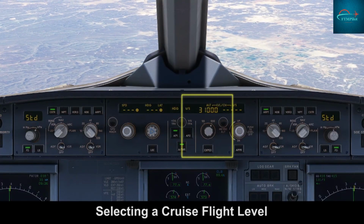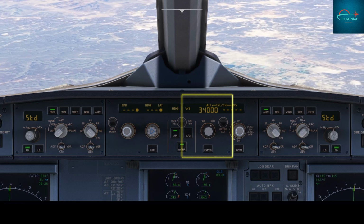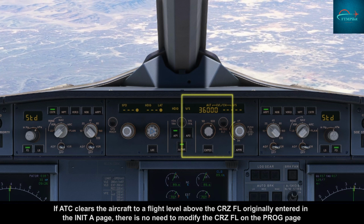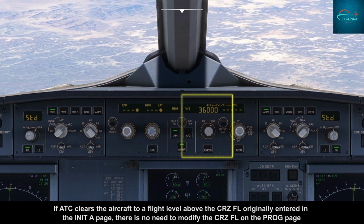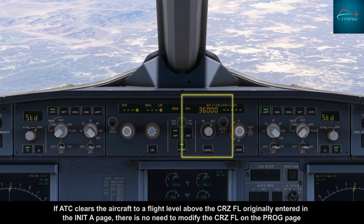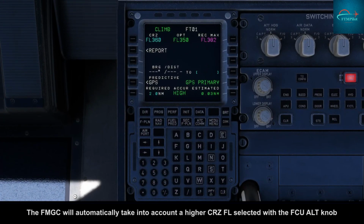Selecting a cruise flight level. If air traffic control clears the aircraft to a flight level above the cruise flight level originally entered in the initialization A page, there is no need to modify the cruise flight level on the progress page. The FMGC will automatically take into account a higher cruise flight level selected with the FCU altitude knob.